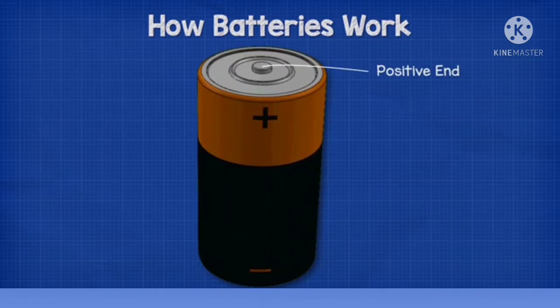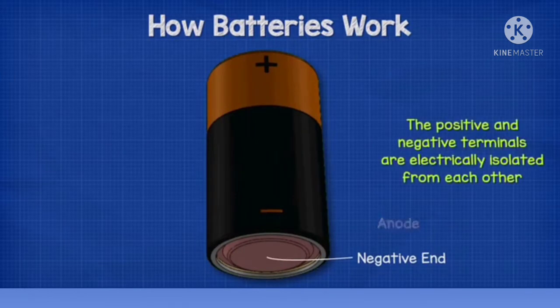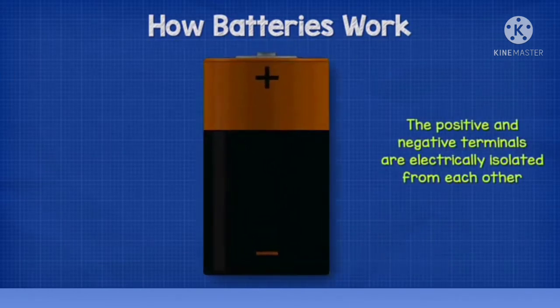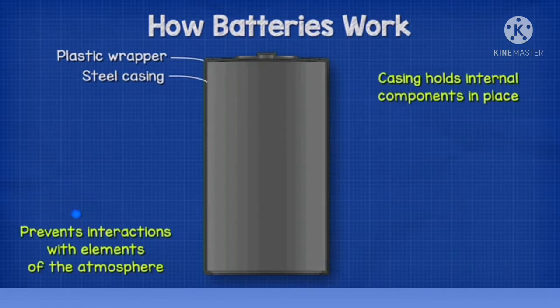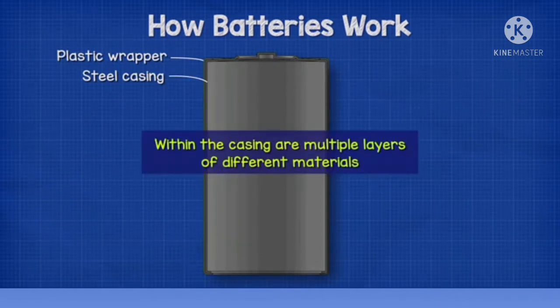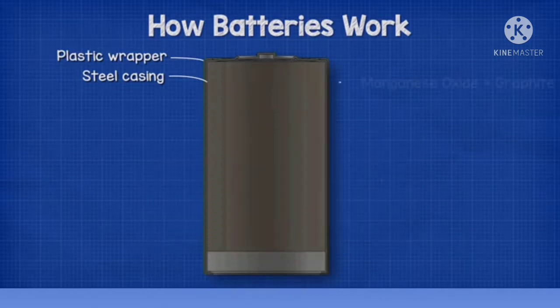For achieving the desired electric potential difference across the battery terminals, multiple cells are connected in series. When the positive terminal of one cell is connected with the negative terminal of the succeeding cell, the cells are said to be connected in series. In this connection, the overall EMF of the battery is the algebraic sum of all individual cells connected in series. But the overall discharged current of the battery does not exceed the discharged current of individual cells.